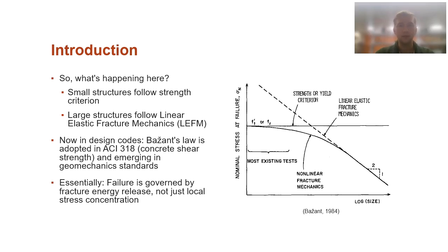And this is becoming a well-accepted thing in the industry. This was originally introduced by Bazant in 1984, but just recently, I think 2019, and we'll get to this in a second, it was adopted into the ACI design codes for concrete. So yeah, it's not just strength. There's also other things going on behind the scenes. So keep that in mind as we go through our fracture mechanics introductions.